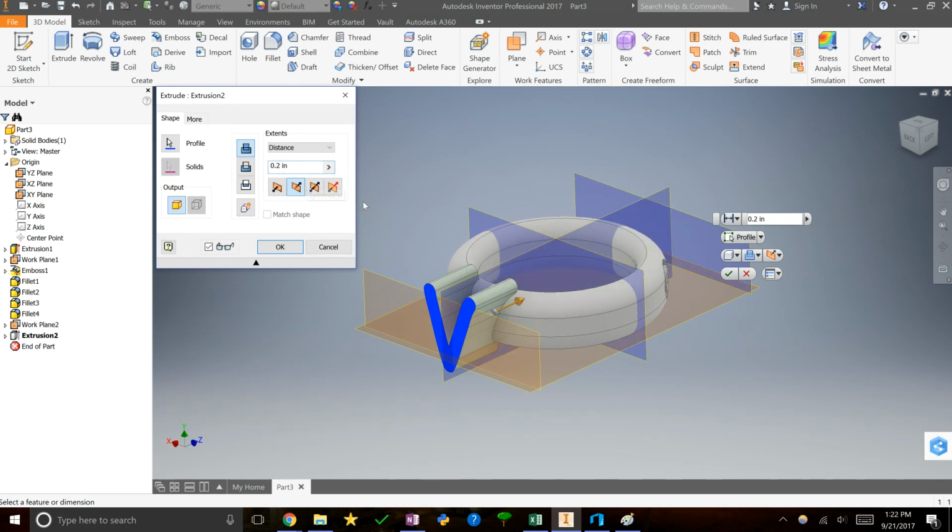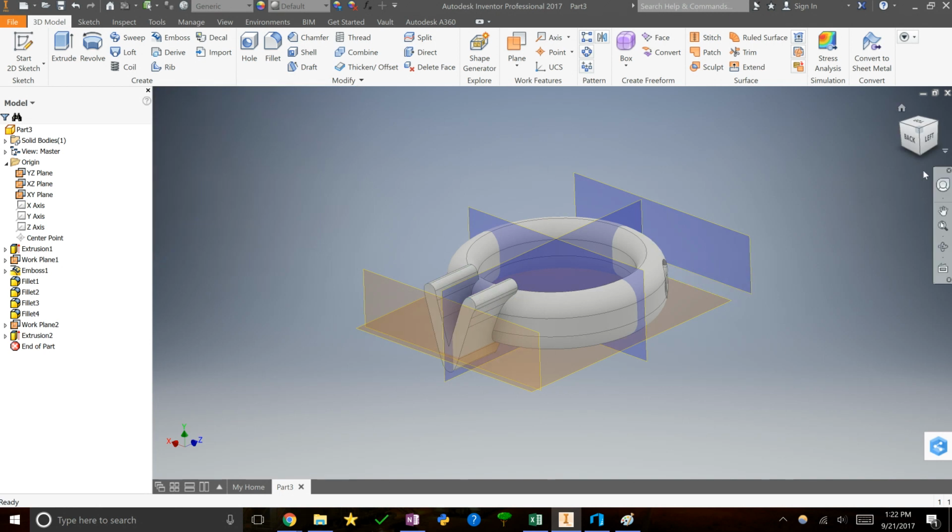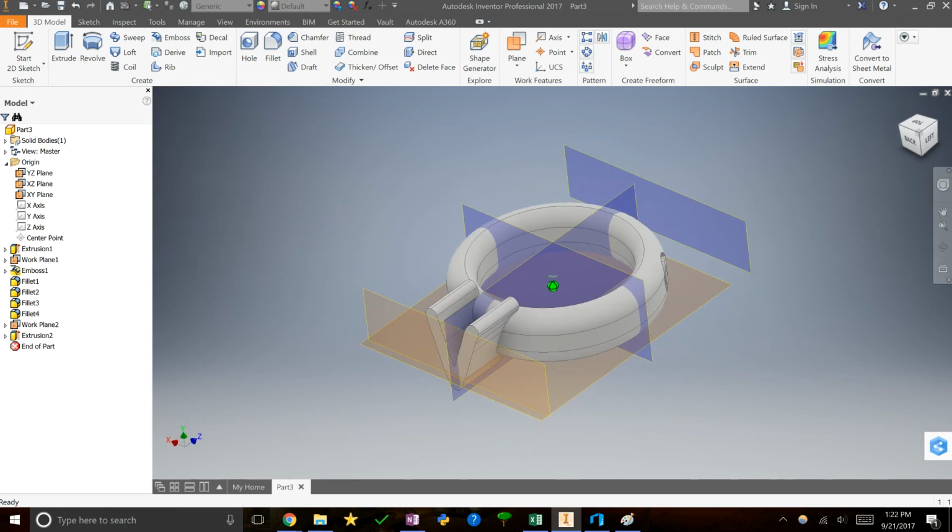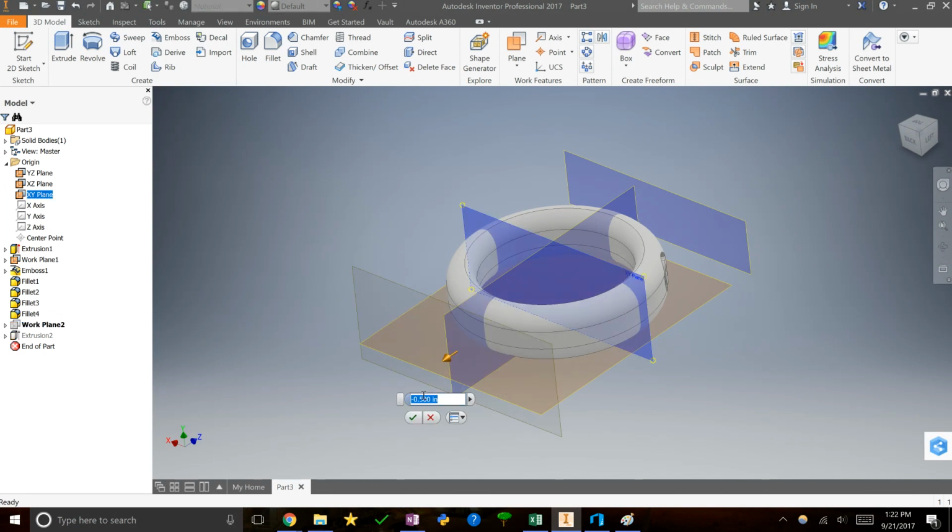Yeah, so this is good, but this V is going to bump into stuff when I'm walking down the hallway. So this is a kind of inconvenient ring. How do I make this not go so much when I start from so far away? Well, I can change where I start from. If I click on this plane, I can hit Edit Dimension, and instead of 0.5 away from this part, I'm going to make it 0.3, say?